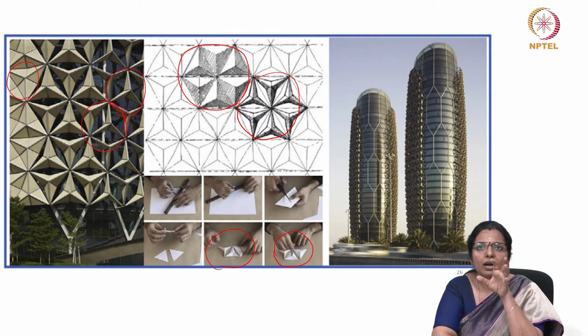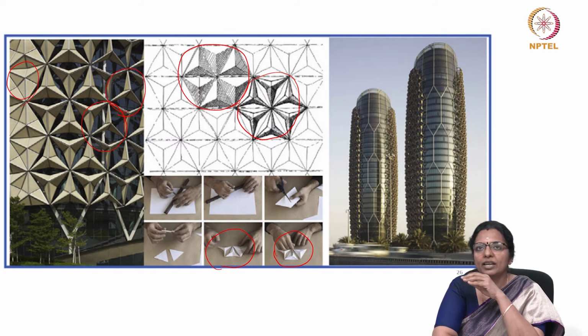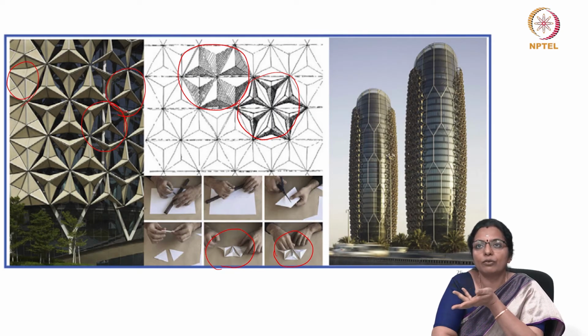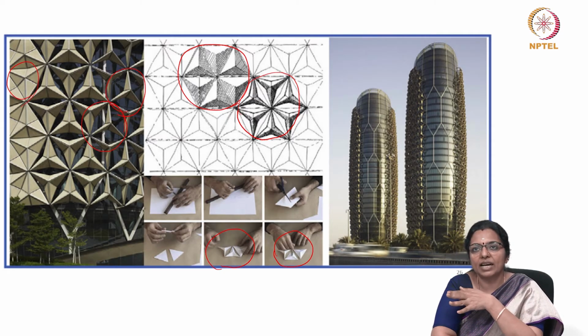So this system has an umbrella like element that will automatically open or close based on the outdoor sunlight, which you want to either allow or prevent from getting inside. So it's an intelligent facade, and it is dynamically controlled by a building management system. So the adjustable shades help reduce interior heat gains which are caused by sunlight, and you are able to cut out these by minimum 50%.